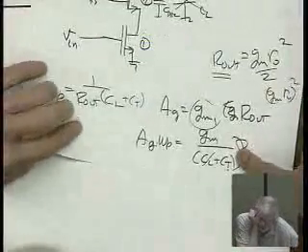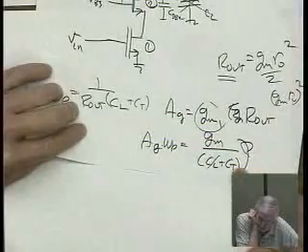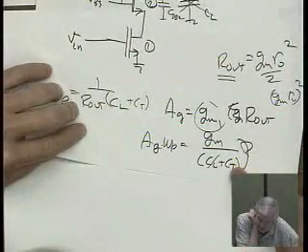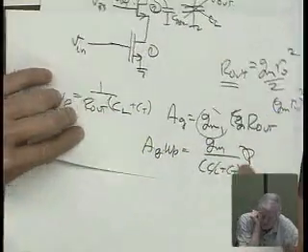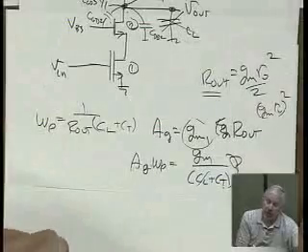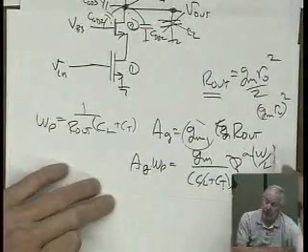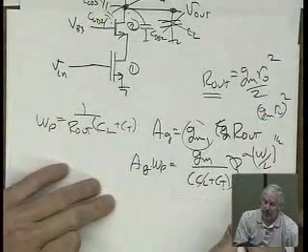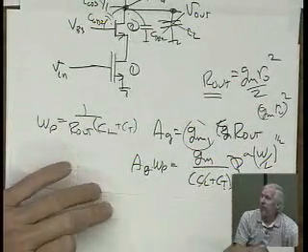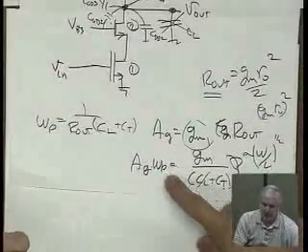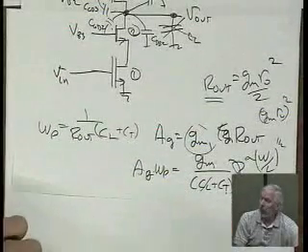So in general, if you increase the W, would you lower this or increase it? It seems like a factor of 2 here, so this thing will go down. Now what happens? So let's increase W. GM goes as the square root of W over L, right? Square root, and then these guys go up by the W. So that means this will go down. This will get worse.